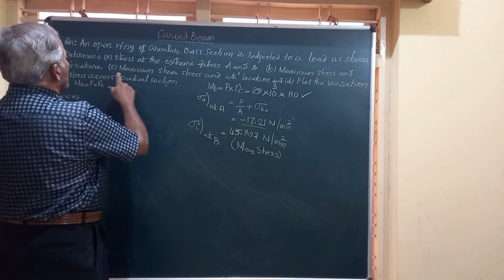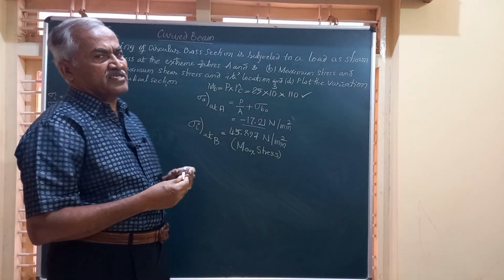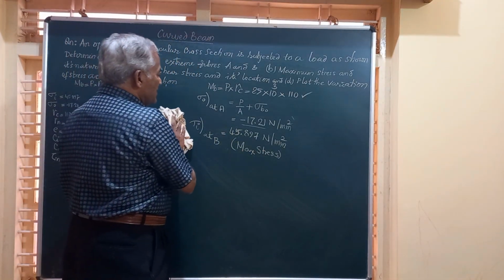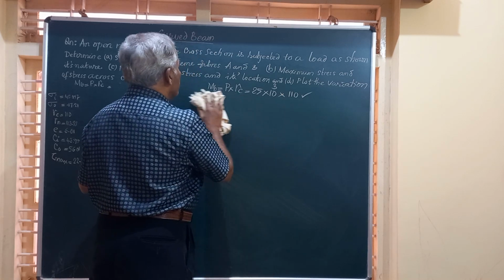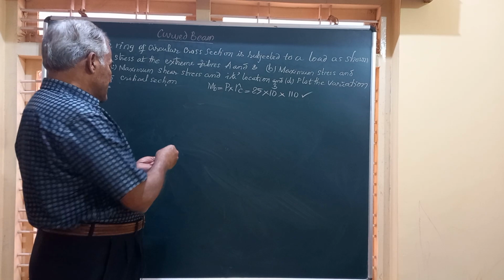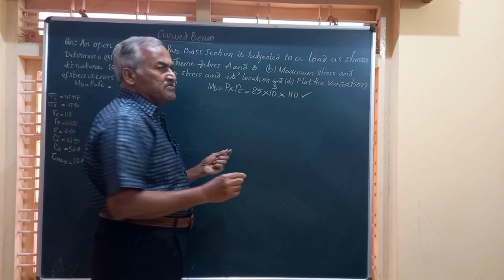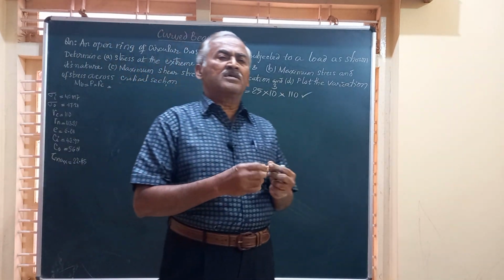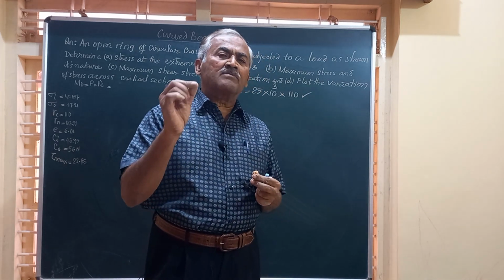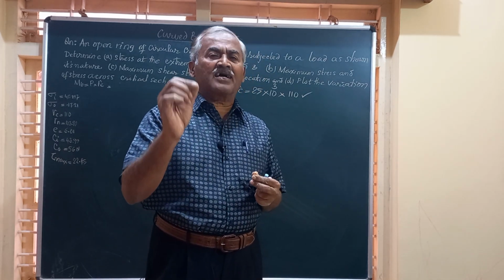Then he is asking you the maximum shear stress. Friends, the stress at the inner fiber is tensile and its value is 45.897. The maximum shear stress occurs where the maximum tensile stress occurs.